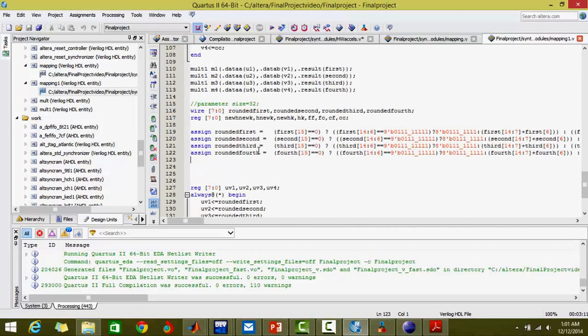Here I have implemented rounding twice, and so my quantization error has increased. But this is what is necessary, because as we don't have floating point arithmetic in hardware, that's why we need to do rounding and saturation every time. And that's why, as I did it a couple of times, my quantization error has increased a little bit.